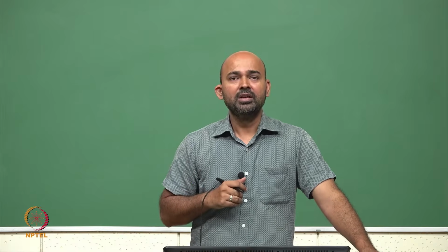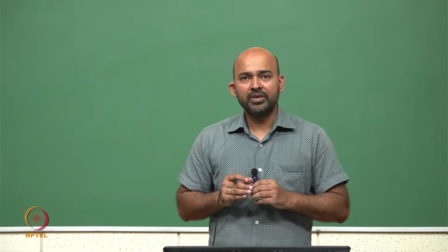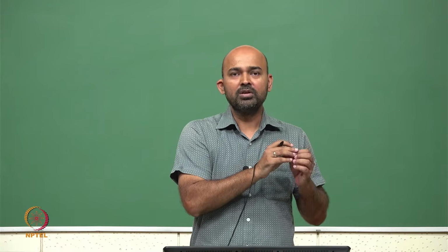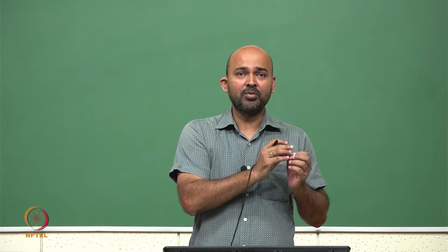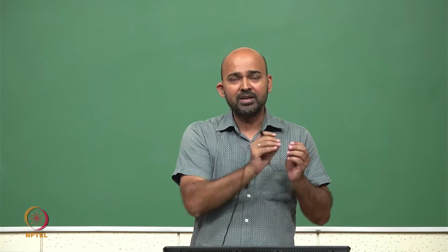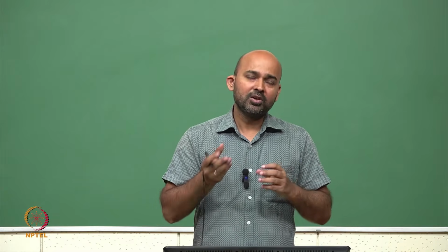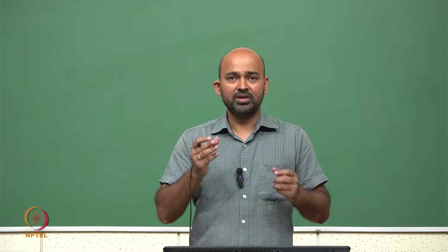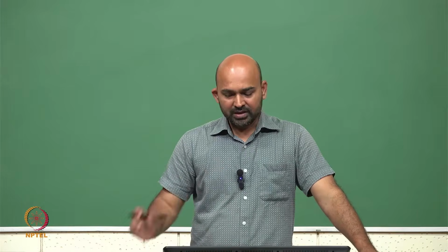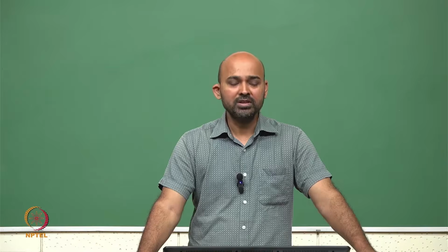It depends on applications. However, delay definitions are quite fixed. From the input when it crosses the 50% point to the output where it crosses the 50% point, that much delay is called the delay of the circuit. And there are two types, one is the rise delay and one is the fall delay. So these are some definitions of the delays in our CMOS inverter.